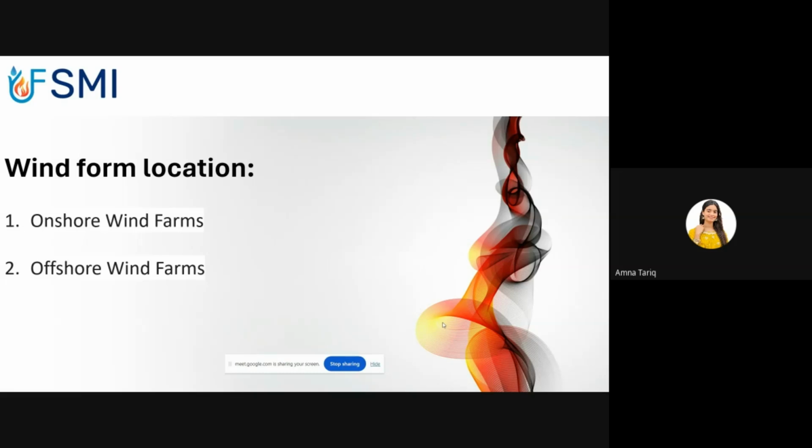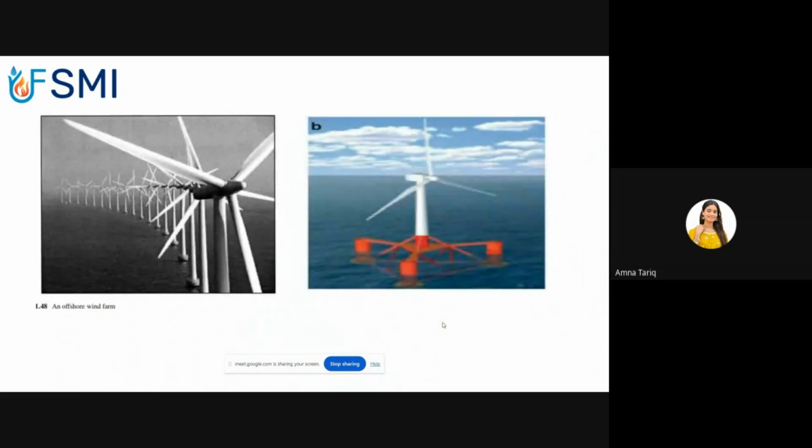The aerodynamic noise, which depends on the tip speed, can be controlled by lowering the tip speed to a maximum of about 60 meters per second. However, in recent years, the size and also the tip speed of wind turbines have increased. The current generation of wind turbines is operating at tip speeds up to 80 meters per second, indicating this noise again may be a problem with respect to public acceptance. So this is the problem of noise. Here you see the offshore wind farms.